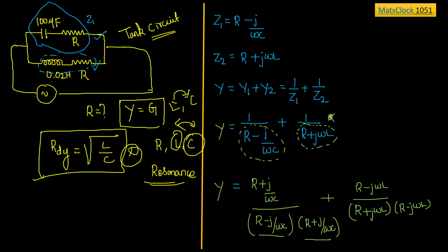Whenever they are connected in series, there will definitely be a chance of getting resonance when we change the frequency. In the question itself, though they have not talked about resonance, they told that this circuit is going to have only conductance. It means the imaginary part of the circuit will become zero. So it clearly indicates that the imaginary part of the circuit is becoming zero only.